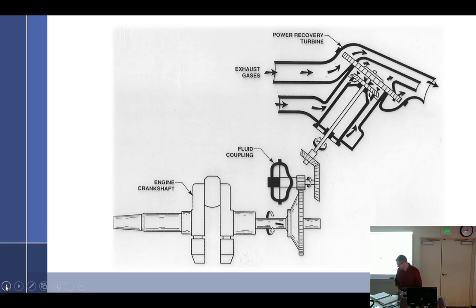Sonic Venturi. Pressurization. Pressurized aircraft use upper deck pressure for cabin pressurization. Use of a sonic Venturi limits the amount of air taken in for pressurization. Upper deck pressure also is used to pressurize magnetos. Forgot to mention that. So if you have a turbocharged engine, there's a really good chance you'll have pressurized magnetos.